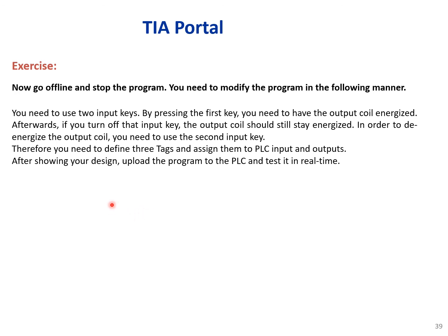Therefore, you need to define 3 tags and assign them to PLC inputs and outputs. After showing your design, upload the program to the PLC and test it in real time. You could easily do that with PLC sim, and I expect students to exercise this program.